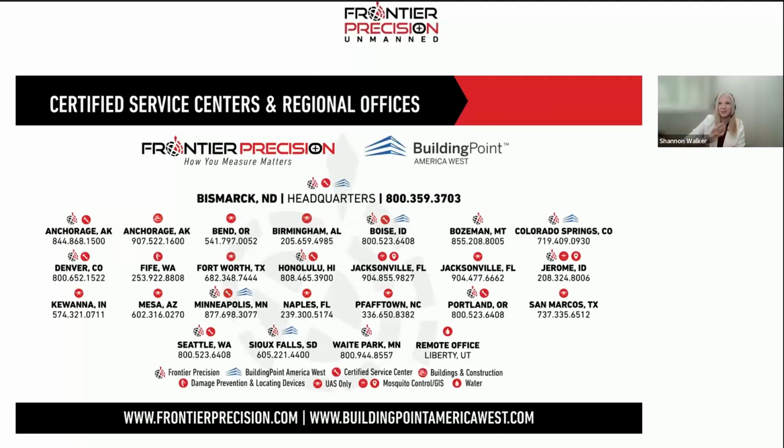Is LiDAR usually combined with other sensors? And if so, what are those? Yeah, it can be. I would say probably the most common integration, if you're doing it simultaneously, is going to be a camera for either colorizing your point cloud or generating an orthomosaic. However, when you combine that, if you're wanting to collect two types of data at the same time, say LiDAR and photogrammetry, we have to prioritize our flight for photogrammetry because the frame of view is going to be different between what your camera sees and what your LiDAR swath is going to cover across the ground.